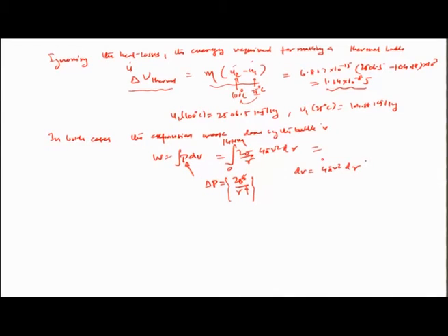So, in this particular case, if we wanted to substitute all the values, the surface tension is 72 times 10 to the power of minus 3 Newton per meter, and obviously the r goes away here, and we are left with a 4 pi expression coming out of the integral times the value of the integral between 0 and 14 times 10 to the power of minus 6 meters.